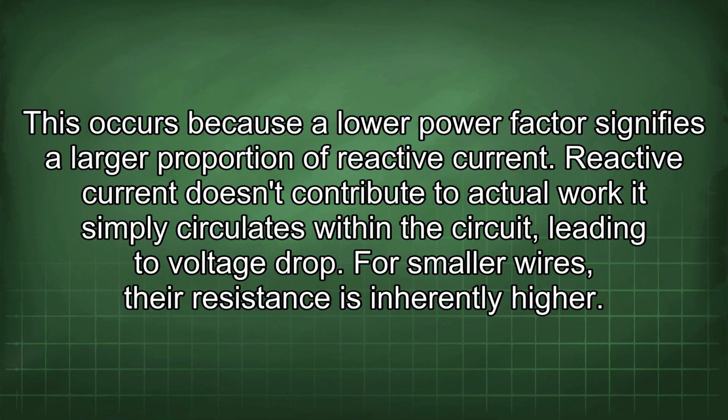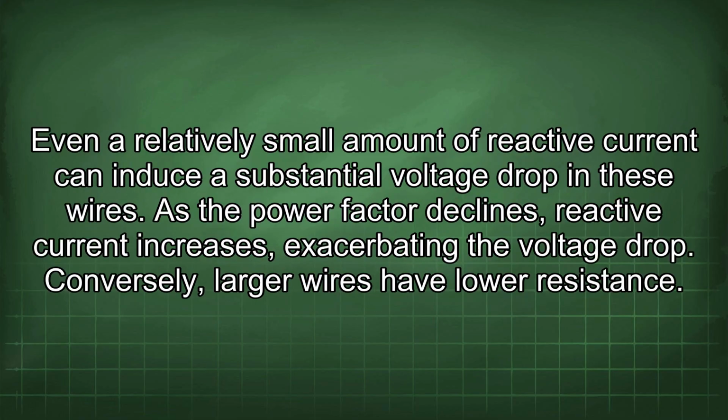For smaller wires, their resistance is inherently higher. Even a relatively small amount of reactive current can induce a substantial voltage drop in these wires. As the power factor declines, reactive current increases, exacerbating the voltage drop.